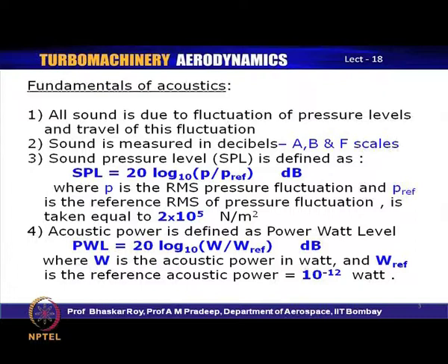So, you see the amount of power that is used by the noise is actually again coming out of the energy that is being transacted within the compressors or turbines. A measure of the power does tell us how much power is literally getting frittered away in creation of noise, rather than being used for purposeful use in aircraft engines. So, acoustic power gives us some idea how the power is going away in the form of noise energy. Now, these are the fundamental definitions of sound pressure level and acoustic power or sound power.